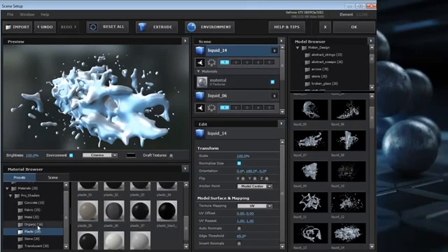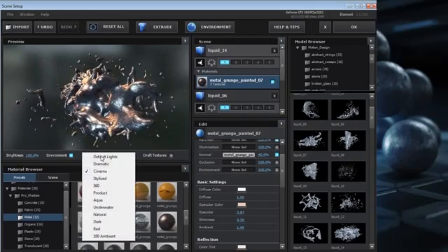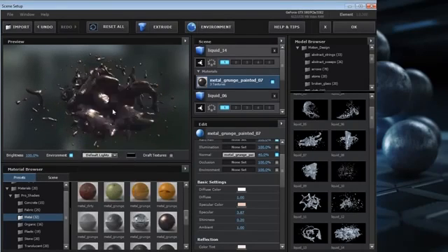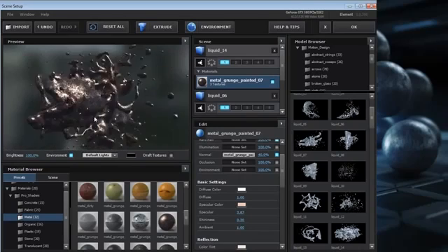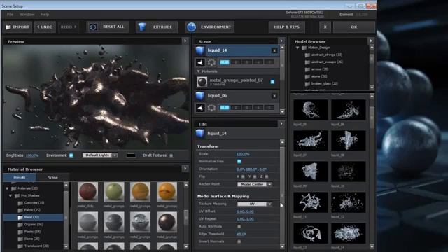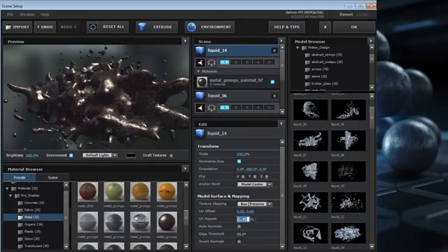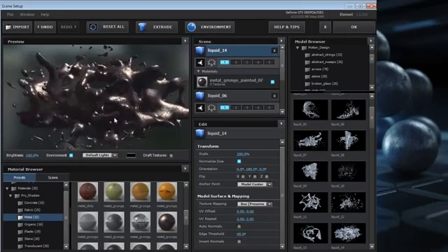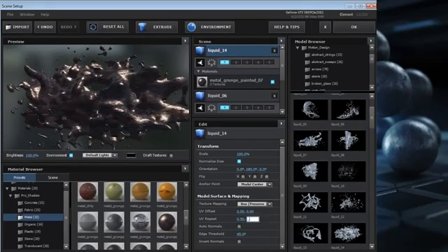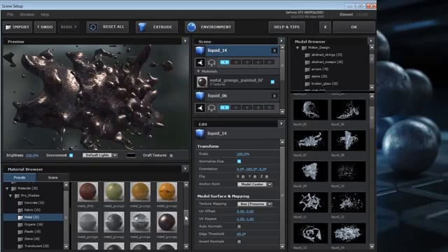They have a basic material. You can go in there, change that out. Now, this brings up another point, is that we have mapping options. So if you don't like the way something is mapped, you can go into the object and you can change it. So we can do just a quick box mode. And if it looks too close together, we can turn up the UV repeat amount, make it a little tighter, or we can lower it to 0.5 and it looks a little bit wider. Of course, you start losing resolution that way.